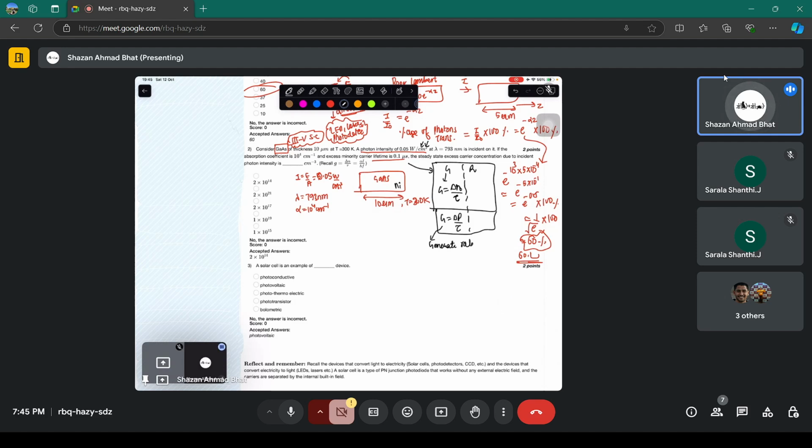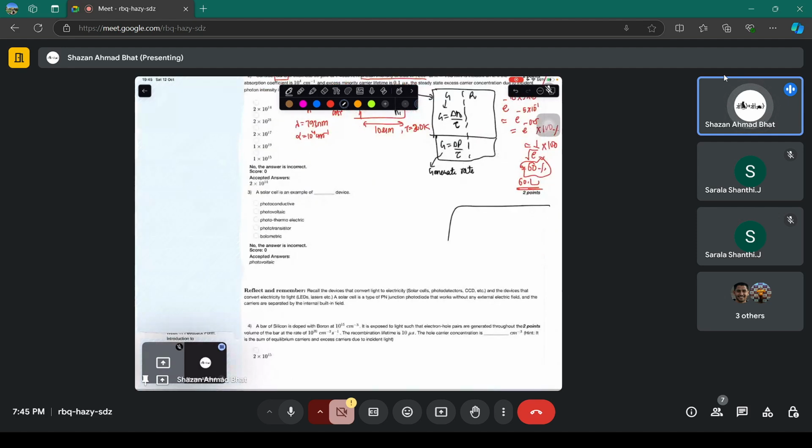This is basically the generation rate, and it comes in the diffusion equation, the rate equation which you studied before, which is D d square n by dx square plus generation minus recombination. This is the exact equation you need to solve in order to understand the electron hole generation and recombination and, I should say, the carrier kinetics, whatever is happening in time and space in the sample.